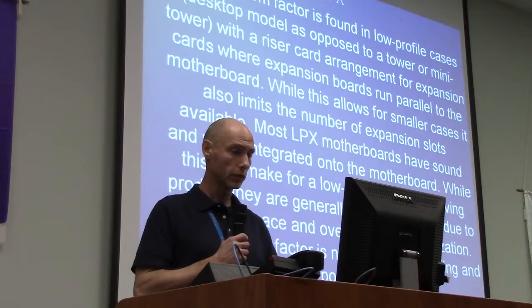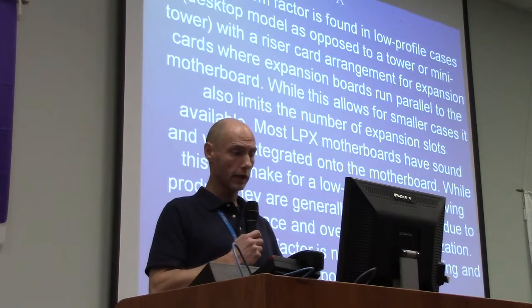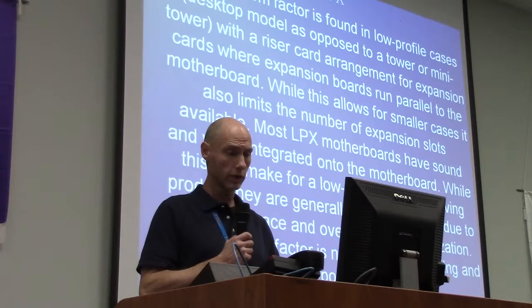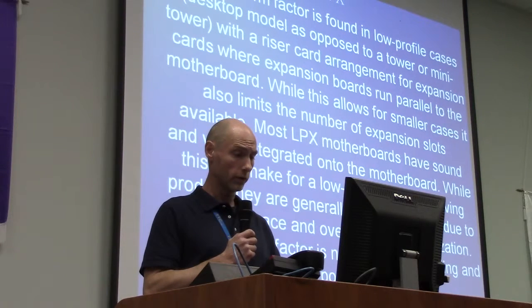Most LPX motherboards have sound and video integrated onto the motherboard. While this can make for a low cost and space-saving product, they are generally difficult to repair due to a lack of space and overall non-standardization. The LPX form factor is not suited to upgrading and offers poor cooling.